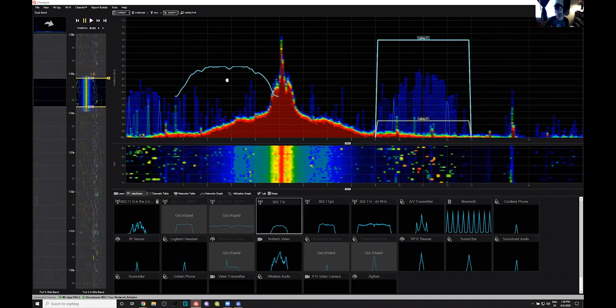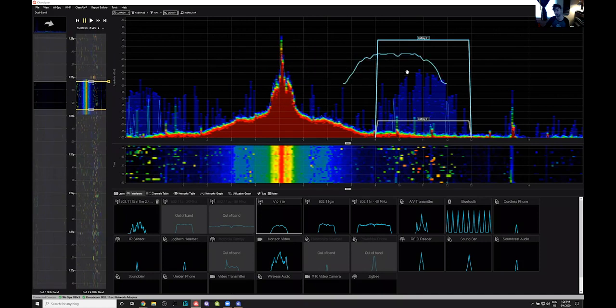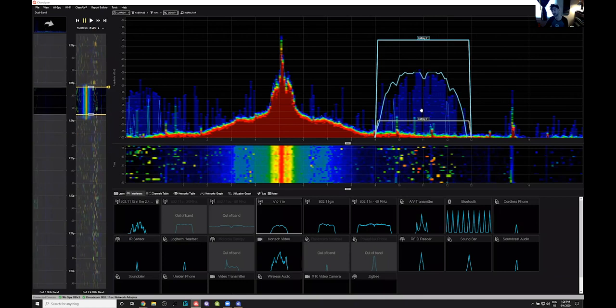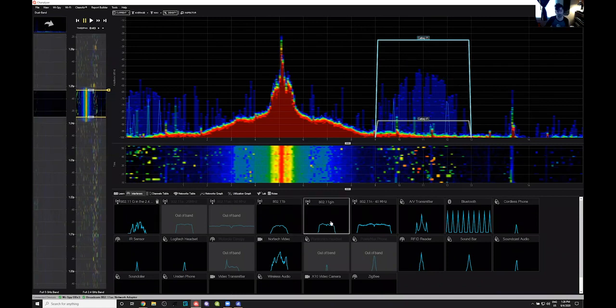And so right now I have some 802.11b signature here, and it's clearly not that, right? This is 20 megahertz wide. It fits more right here, right? And if you scroll, you can kind of manipulate the height of it, which is pretty neat. And so you can see that matches pretty well some 802.11b activity like I was talking about earlier with the DSSS modulation. Clearly not that. It's kind of fun to play with these signatures, because if you aren't familiar with them already, it's really good to kind of know what they look like.